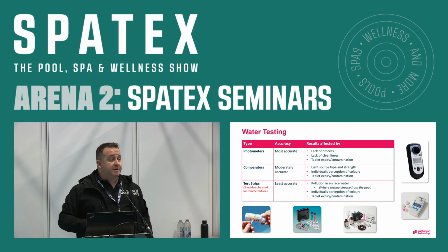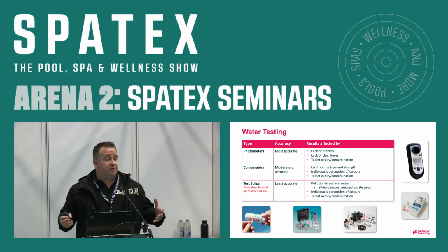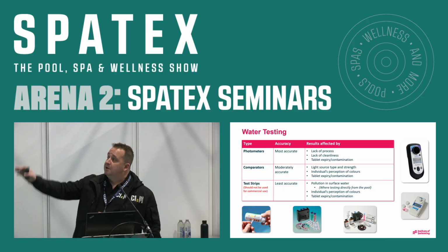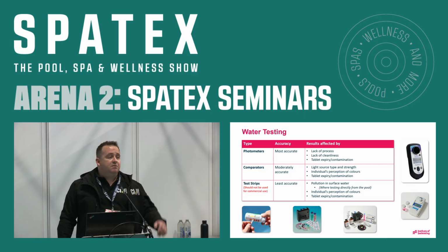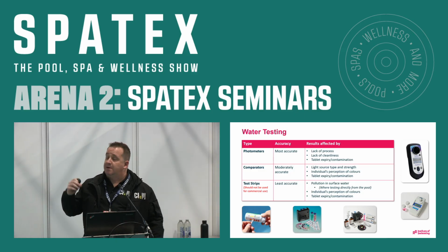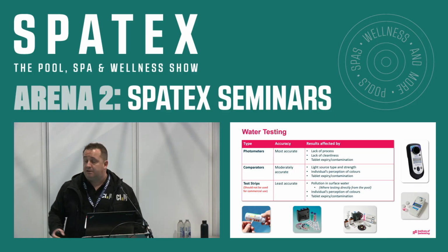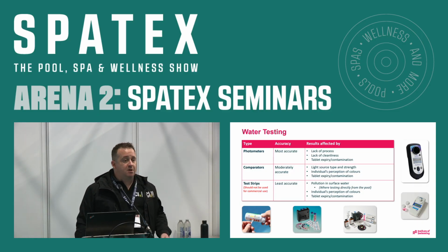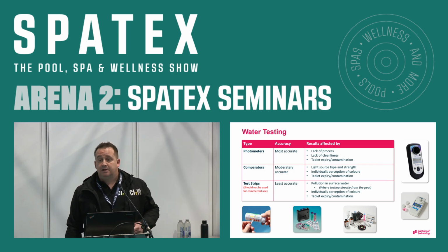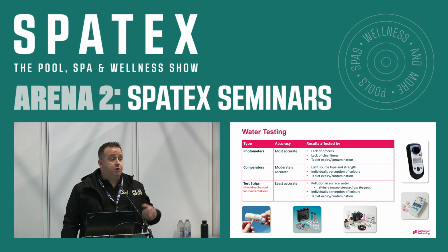Comparators, a bit old school now, okay, but this is what we played with all the time when I first started. Comparators, as we see here, okay, moderately accurate. They do have their place, definitely. They don't really let you down, but they are affected by your light source, for example the light coming in from the back of it.